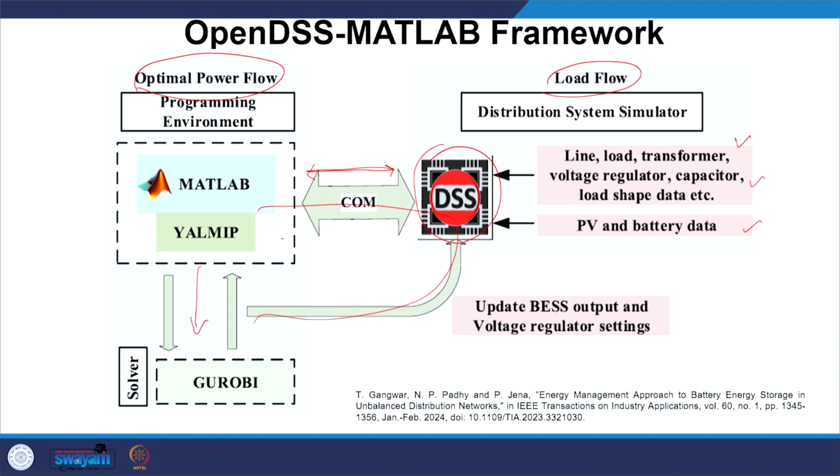So MATLAB can engage both DSS and Gurobi to carry out any optimal power flow or load flow analysis of distribution networks through modeled network parameters and data made available to me. For example, for the IIT Roorkee distribution system, I can obtain the voltages at each and every load bus, subject to the modeling being correct and the software platform being used to simulate the data.